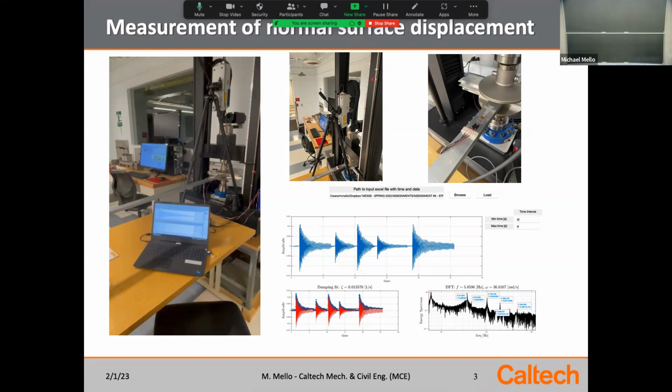And what you're seeing here, way out here, are higher modes that are super weak in reality, okay? The dominant mode is probably this mode, right? This flexure mode that you see and you imagine with your eye, but superimposed on it are these other modes of much smaller amplitude, but they have the S shape and other shapes. And this is a log plot of the energy spectrum. So to draw these out, you have to use a log-based plotting curve, and then out are coming some of these higher order modes that are present, okay?